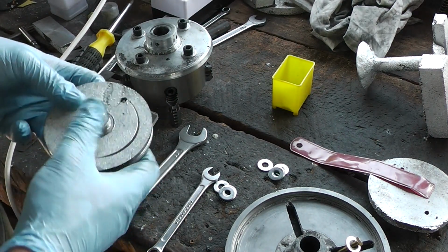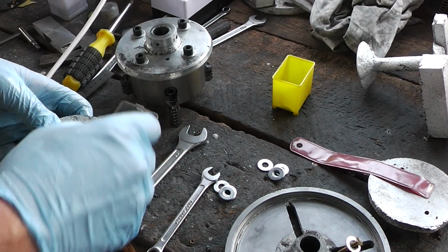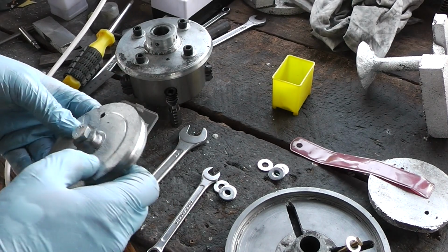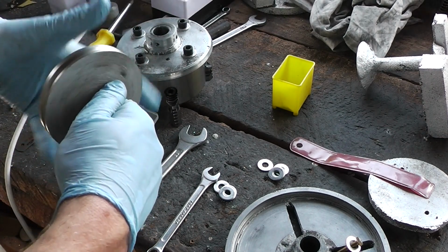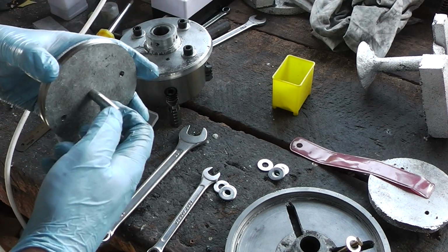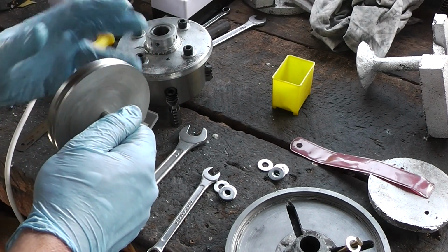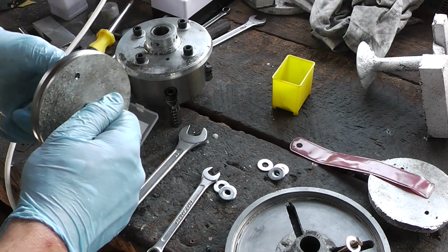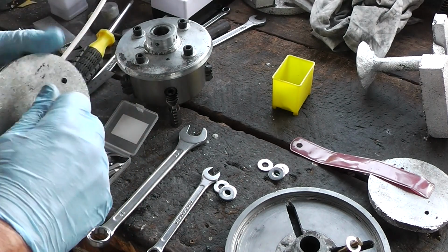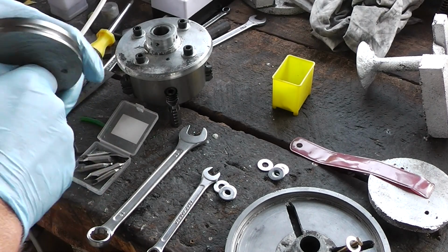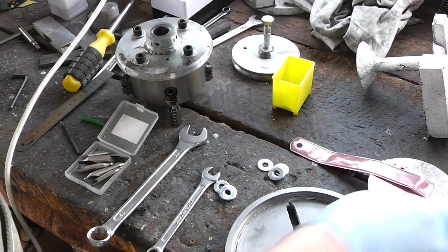Okay, I definitely lost concentricity there when the facing operation hit that screw head and got all boogered up, but for my purposes this shouldn't be turning fast enough for it to be a problem. There's extra space there, so I've got some nylon and steel washers I'm going to use for thrust bearings on it. Probably won't be turning fast enough to need a bearing in there. So maybe tidy it up a bit with the file, but otherwise that's that one done.